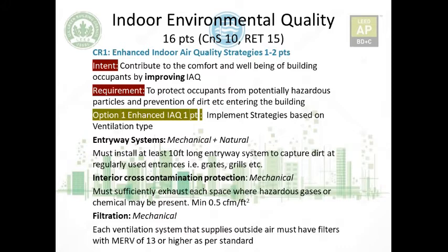Now you know that it is for the entryway system, preventing dirt or any hazardous particles from entering the building. So you put a small space at all the functional entrances, so that if there are any contaminants, they can be sorted out before they enter the building. And these carpets, grates or grills have to be cleaned at regular intervals, I think minimum weekly.